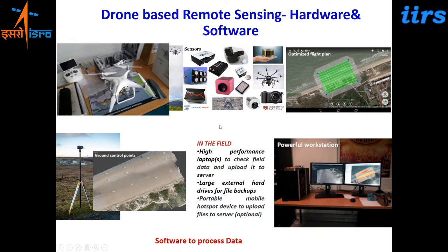Then the success of any UAV campaign depends on the pre-flight planning. Where is the data you want to acquire? Which are the areas? What is the resolution? What altitude will it fly? All this planning has to be done. For that, every drone has a mission planner, right? And this makes it much easier for you to operate the drone. So once you plan your mission properly beforehand, then the entire process of data collection is very, very easy.